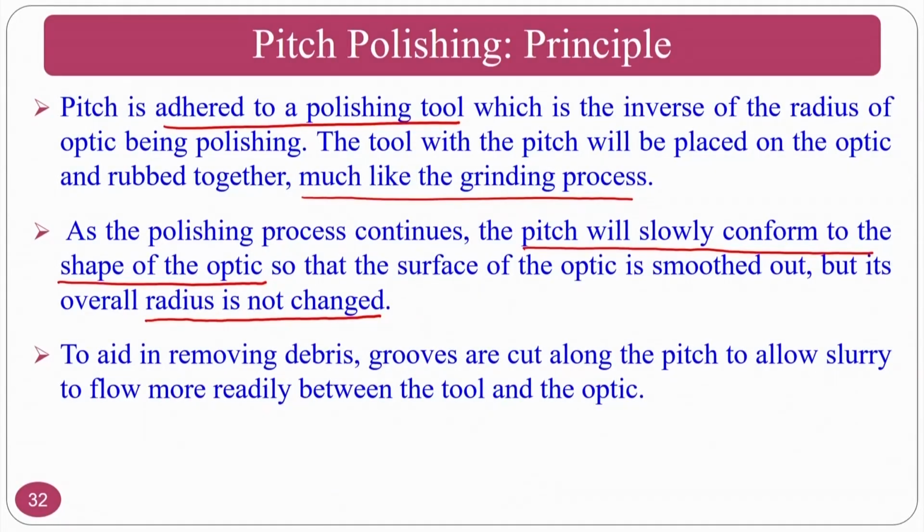And to avoid removing debris, grooves are cut along the pitch to allow the slurry to flow more radially between them. Normally you can give some scratches on this pitch. Normally, if you see, the polishing tool will be like this, wherein the pitch will be there.